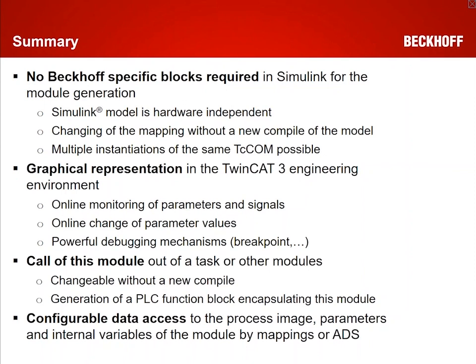And of course, like we've seen, we generate out of the box PLC function blocks, the PLC wrapper. And they provide you the possibility to configure data access to the process image, to the parameters, internal variables of the models by mappings or ADS. So all these things that we have seen under TC interfaces.